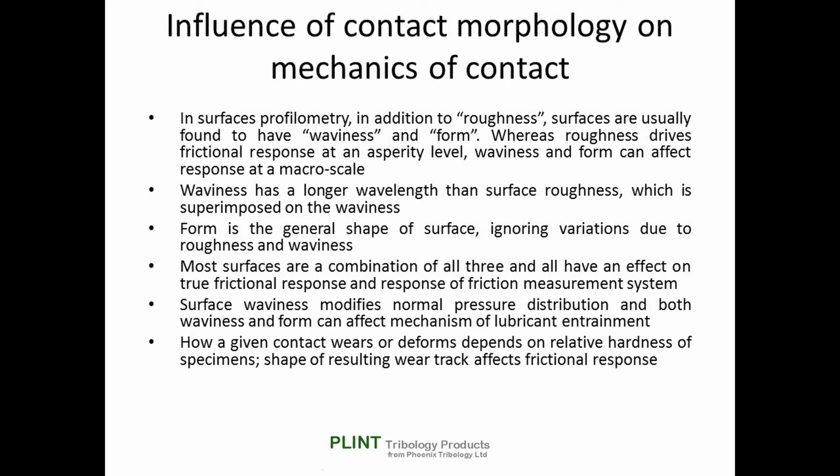Now let's consider the influence of contact morphology on the mechanics of the contact. Greenwood and Williamson provides the basis for the modern understanding of the role of surface roughness, hence asperity interaction, in frictional response. The term nominally flat in the title of their paper refers to the fact that the reference plane in their model is flat, but with superimposed surface roughness.